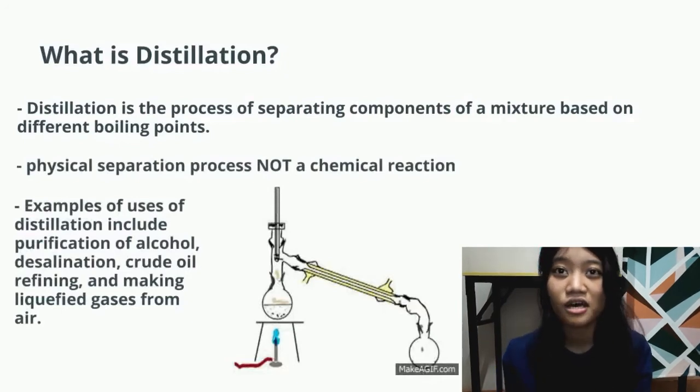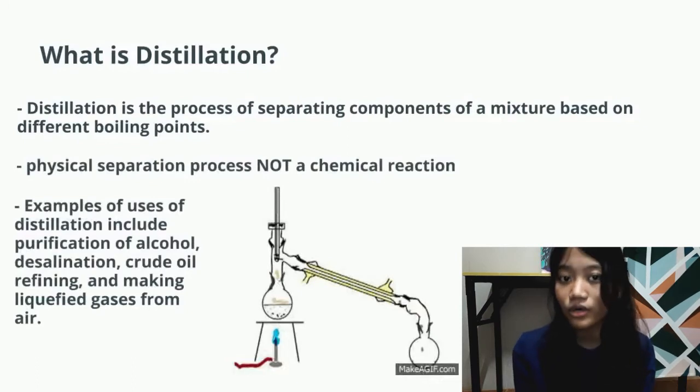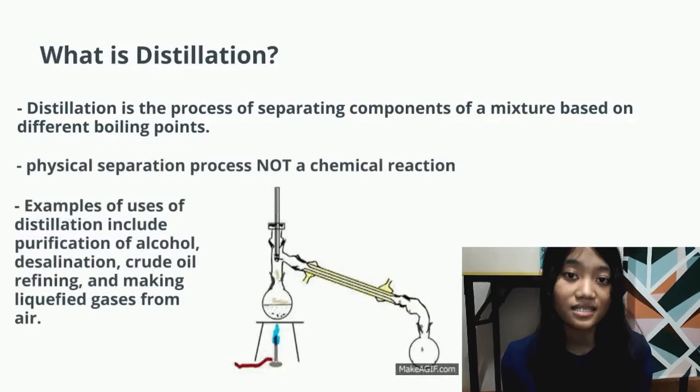Distillation is based on the fact that the vapor of a boiling mixture will be richer in the components that have lower boiling points. Therefore, when this vapor is cooled and condensed, the condensate will contain more volatile components. At the same time, the original mixture will contain more of the less volatile material. Distillation columns are designed to achieve this separation efficiently.